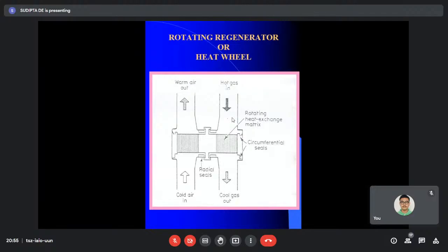So depending on the type of process, if your subsequently heated gas is fed back to the same system, then there is no problem, because contamination was there in the hot source gas, and the contamination is partially transferred to the cold gas. After heating, heat is regained, and simultaneously that contamination is also partially transferred. Say in the hot gas it was 100%, but in the cold gas it is, say, 40%. So obviously if you feed that heated gas back to the same system, it doesn't make much difference, because the same contamination was already there previously. So this is basically the philosophy of using regenerators.